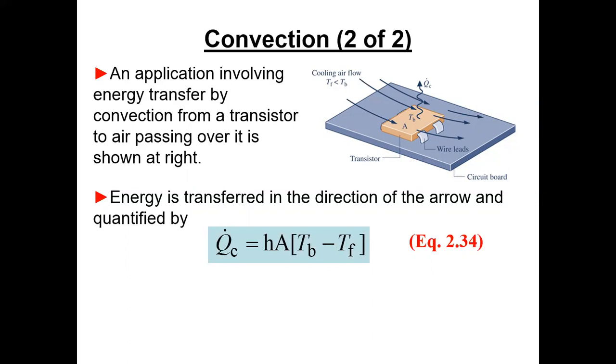But then in your case, where you're trying to do this calculation, the air is coming through a case and all this sort of thing, and the velocity profile gets all chopped up. So that h that you calculate from that nice velocity profile may not be very close to the h you actually have.